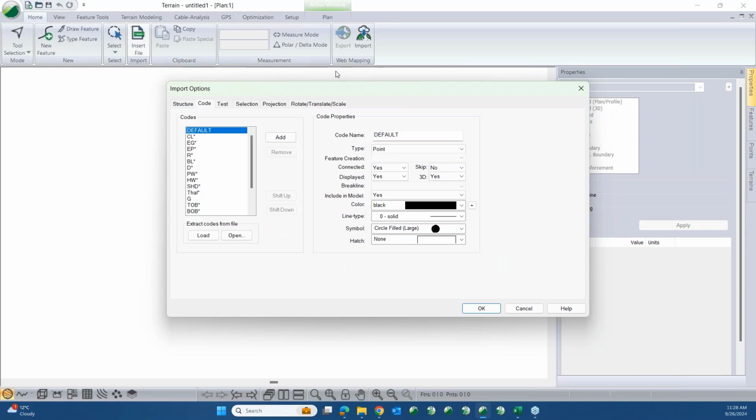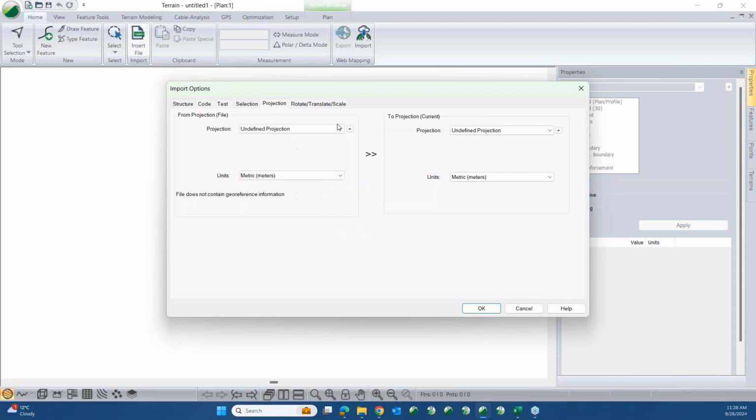So with this, if our surveyor surveyed some CL points, those CL points are going to be connected as a break line with a red dashed line and triangle appearing at the survey points. Whereas if they surveyed, say, a line that's called BL, it's still called out as a break line, with different symbology though. And then my fence is not a break line. So we can really streamline applying the format, so when we do bring it in, there's no messing around with connect the dots.